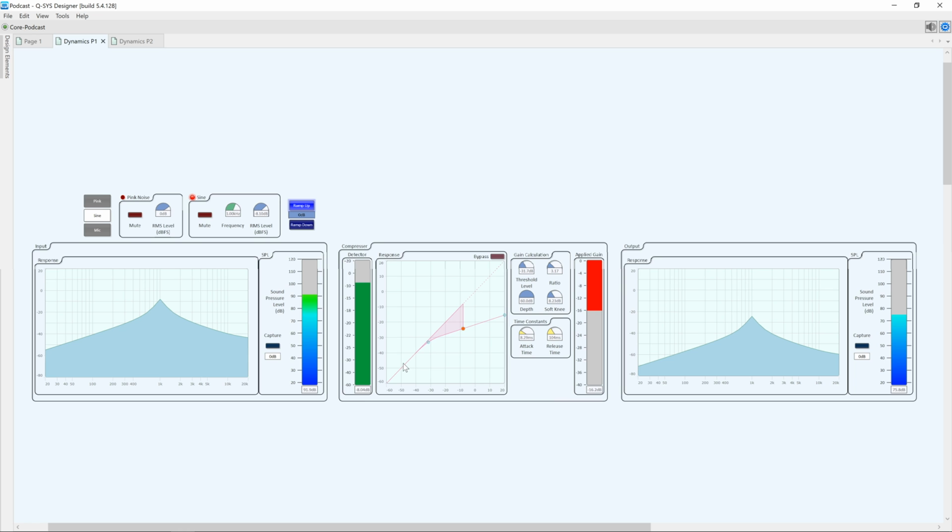So you get the dynamic range down low, but reduce it towards the top end. Usually you can do a threshold of negative 25 or so, and a ratio of 3:1 for voice. I'll do a softer knee, nothing too dramatic, and I just leave the depth by itself. No need to change that.